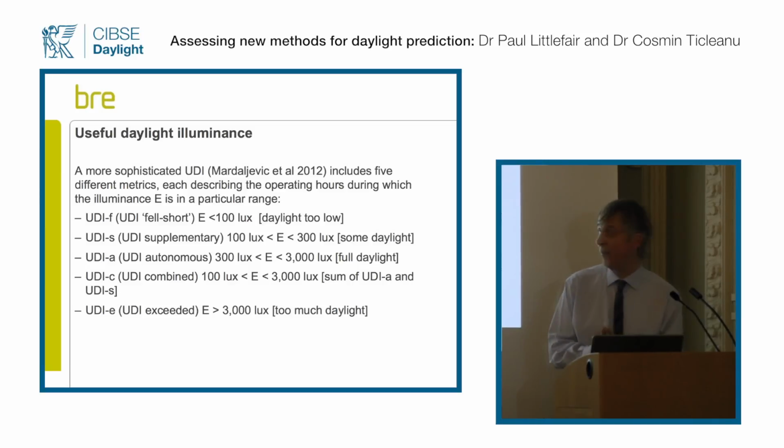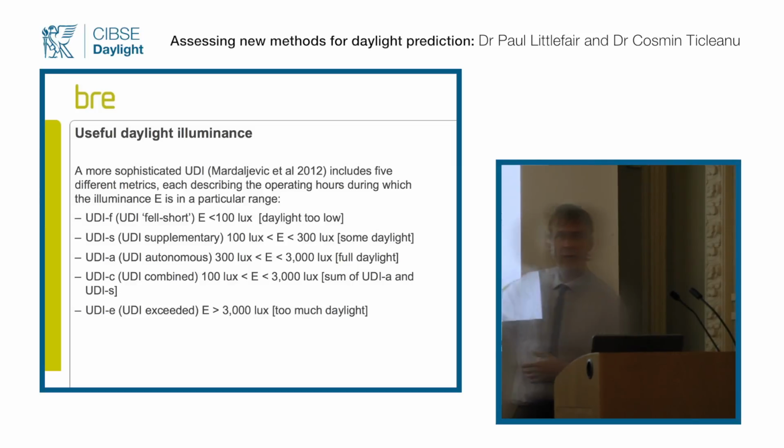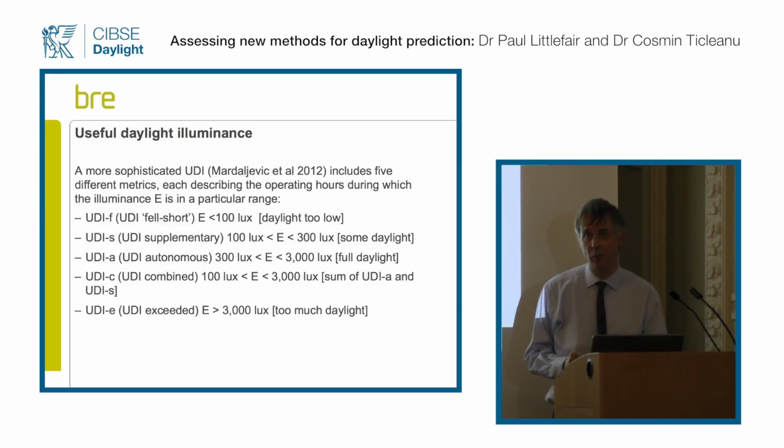But I think you're right in that what it does is it tells us that we've got too much, which the daylight factor never did. You'd always be thinking, oh, well, I've got to meet this particular daylight factor, so you could chuck glazing at a problem, and then you get into this sort of area where perhaps you get a room which was equally unsatisfactory, but because of sunlight and glare rather than because of lack of daylight.